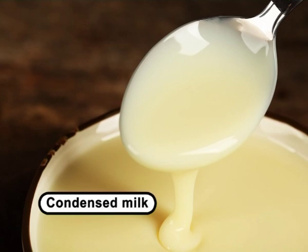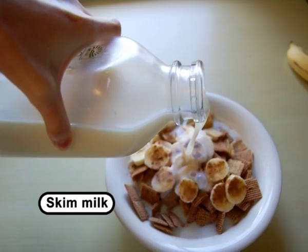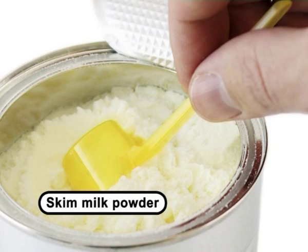Since lactose in condensed milk is at supersaturated level, seeding of condensed milk with powdered lactose is done to avoid formation of large lactose crystals, which is objectionable. Production of milk powder. The excess milk is separated into cream and skim milk. The cream is converted into butter and skim is converted into skim milk powder to conserve the milk solids. The butter and skim powder are used in various food formulations.